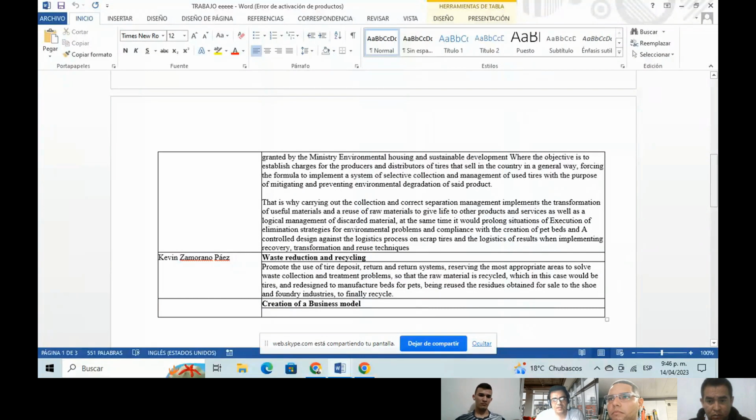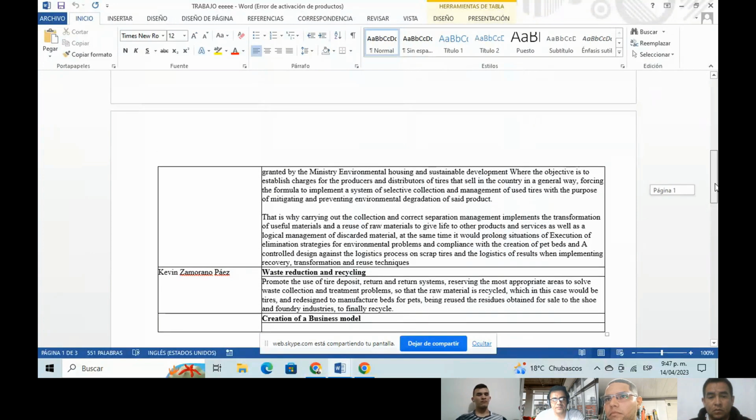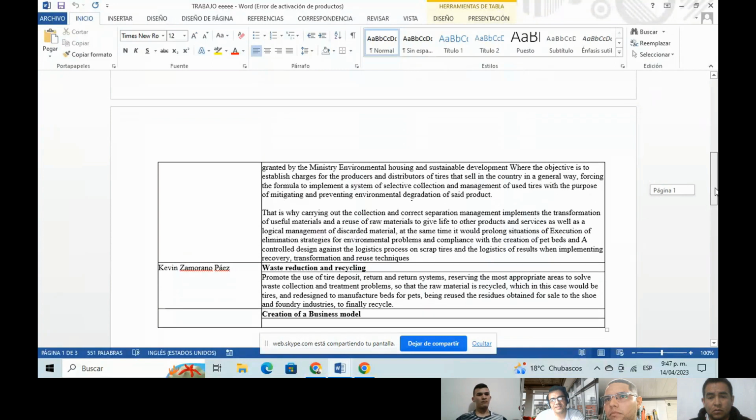One of the steps will be acquisition of high efficiency equipment, replacement of 40 watts and 36 watts fluorescents by 28 watts as a corrective maintenance activity, which does not represent any investment.